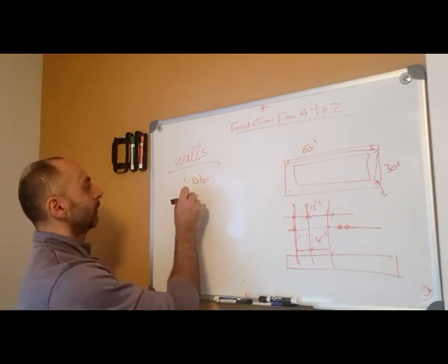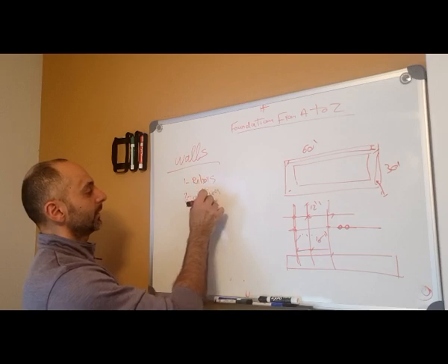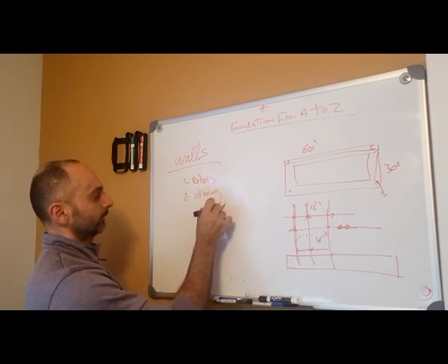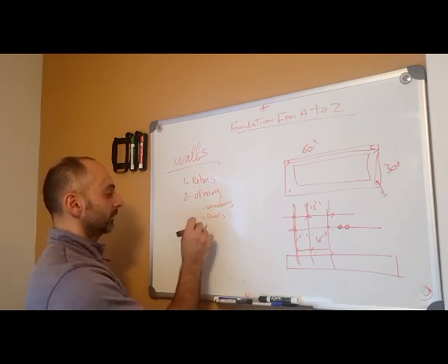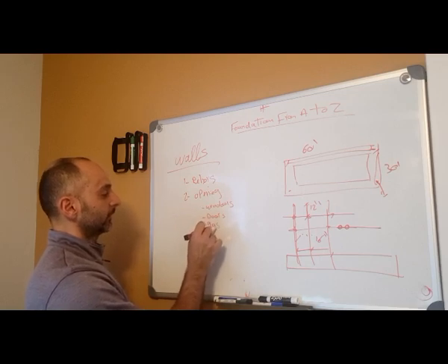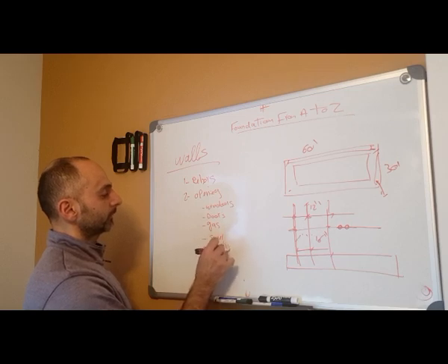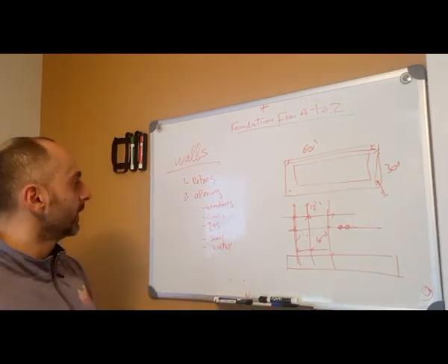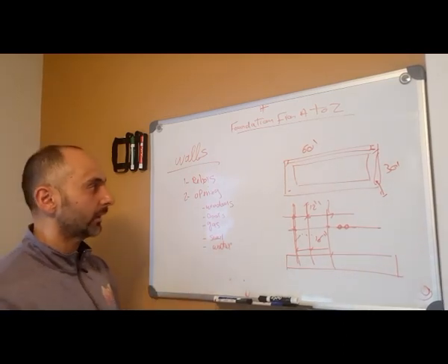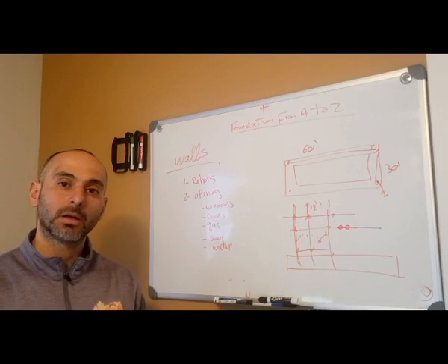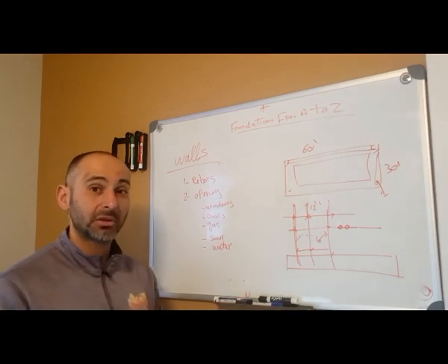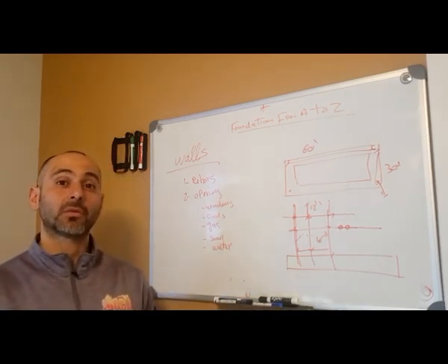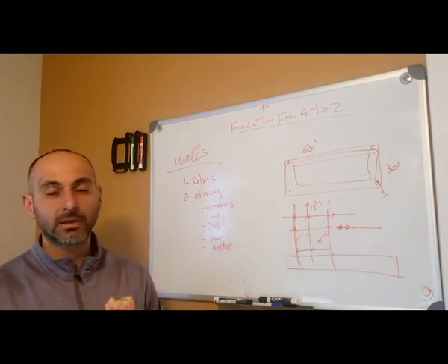Rebars to openings is very important: windows, doors, pipes, so gas, sewer, water, or any other pipe. Make sure your contractor does all the roughs on the windows. You give him a window schedule, or it is on the plan. For any windows in the basement, make sure he roughs them in right, with pressure treated wood, and does flashing around the window openings.